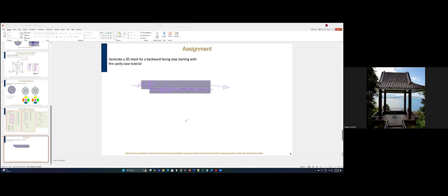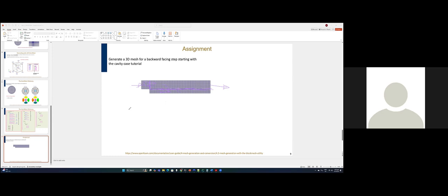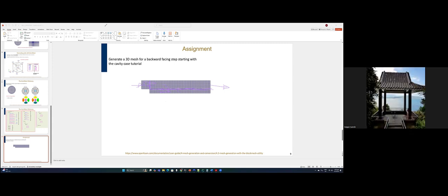And with the link I shared in the WhatsApp, you would see it there. So just make sure that you follow that, and that should be it. That's the only tricky part. You get it? Yeah. So meshing is the most critical point: your geometry and your mesh. Once you've been able to do that, the rest you can just follow the various case files and make sure that your boundary conditions and the names of your patches actually match. And that is it.